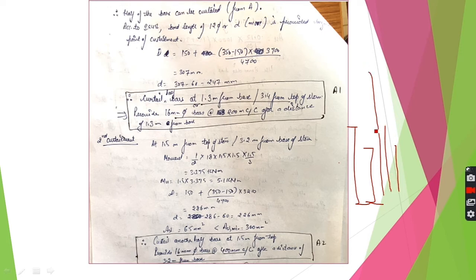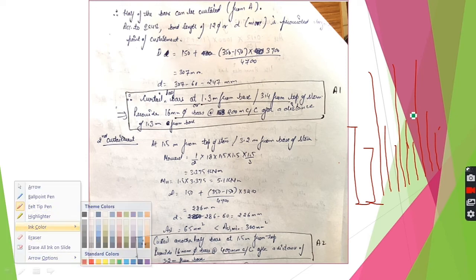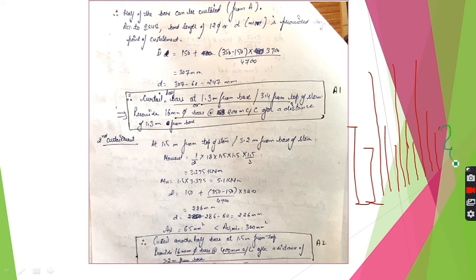height. So as you can see here clearly, if we repeat it alternatively, in this portion, it is the lowermost portion of your cantilever wall, we are getting dense reinforcement with less spacing, which is 100 mm.